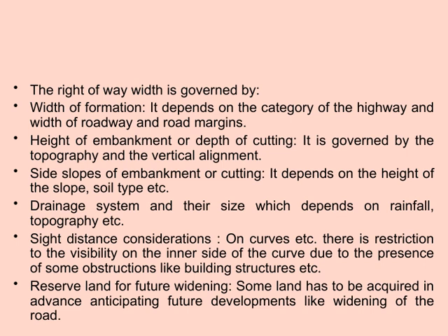Lastly, we should reserve land for future widening. As traffic grows and development progresses, roads often need to be expanded. Acquiring some land in advance helps facilitate future widening projects without significant disruptions or additional land acquisition costs. Overall, these factors are interconnected and vital for designing a safe, efficient, and sustainable highway. Understanding them ensures that we allocate the right-of-way appropriately, balancing current needs with future growth.